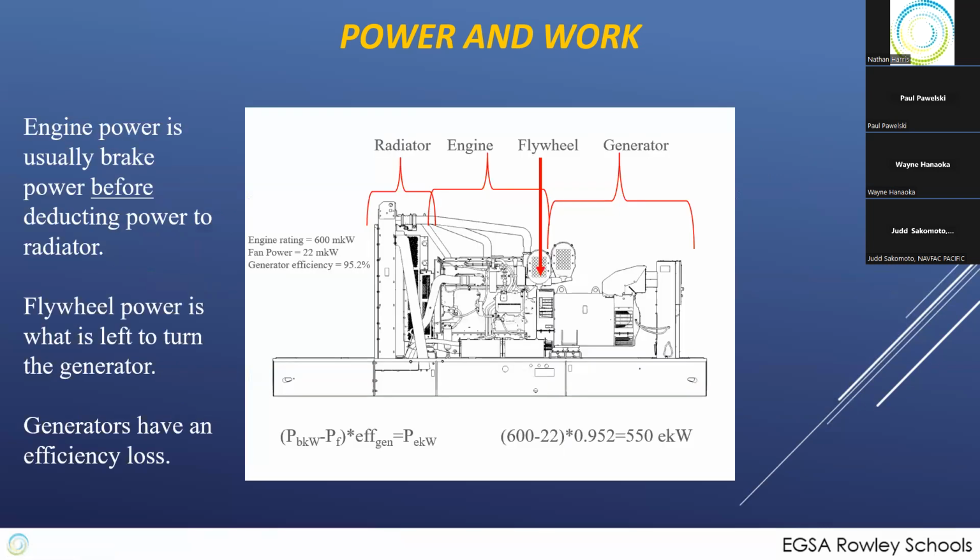All right, last thing on here. We want to figure out how big of a generator you need, how much power you need, how big of an engine. Well, engine power is usually measured in brake power. That's the amount of power that in the factory, when they hook the engine up to a pony brake and run it the first time, it puts out.